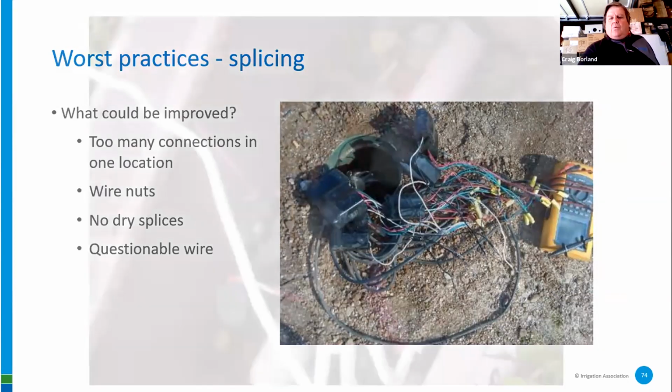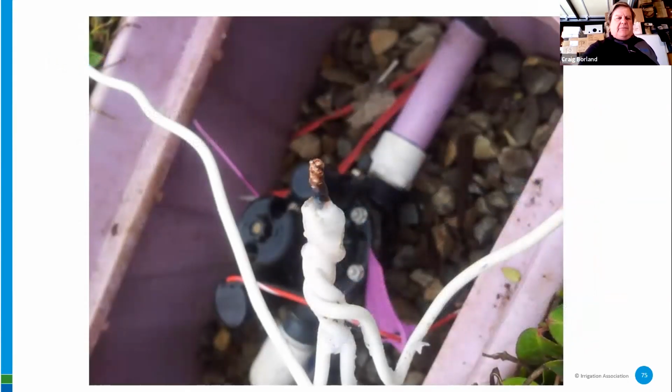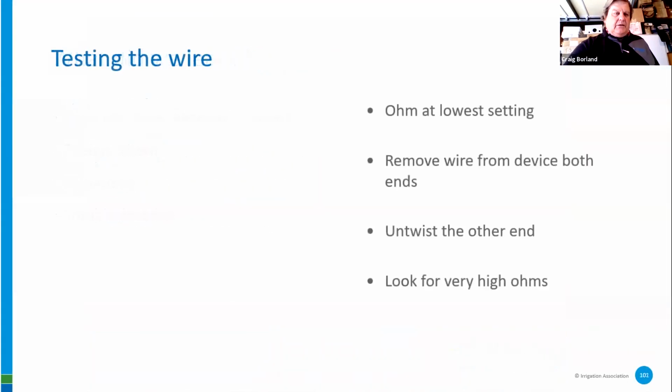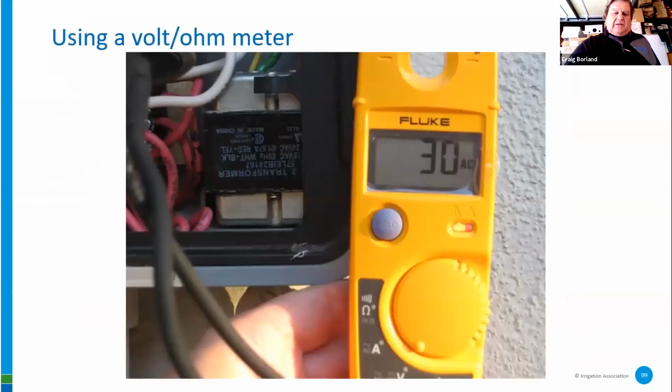So guys, wire nuts, they need to be good. This one, you can see the plier marks on the wire, twisted so bad, but still yet, moisture got in there. I see the black spot. It's beginning to corrode. So knowing where we are in the time, let me bump ahead, go back a couple here and talk about this last thing.